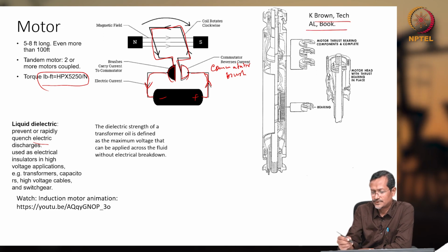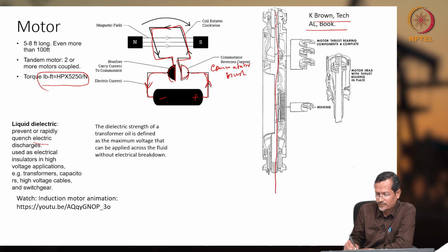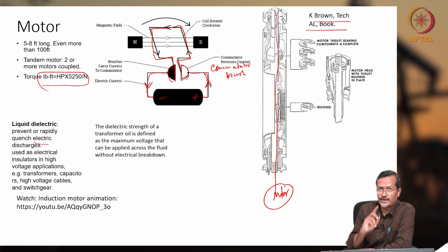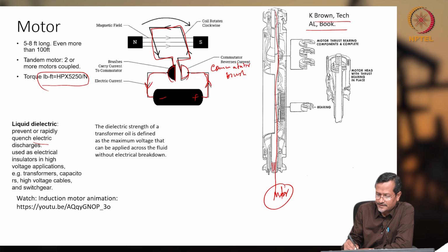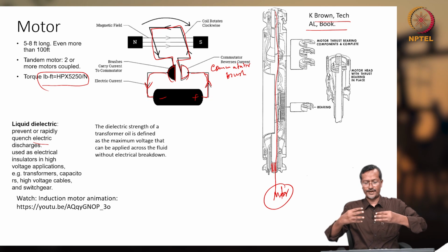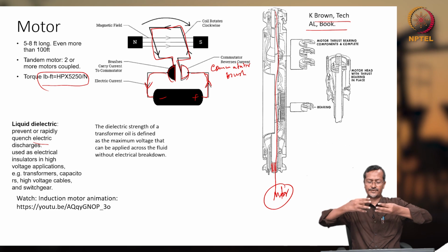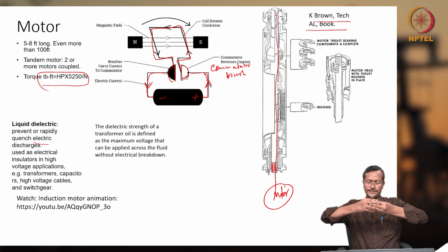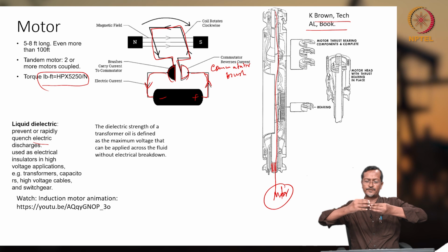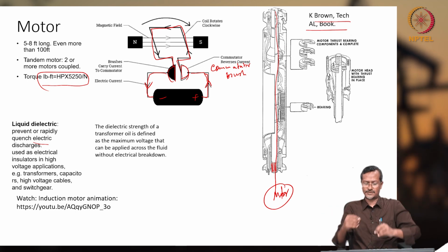This picture shows one big shaft going from the motor. The motor will be giving torque. And this will be the connection, the motor coupling. So how to connect: one motor shaft is there, one turbine shaft is there, your pump shaft is there. So the pump and motor shafts will be connected like this, and then you will be rotating. Maybe there will be a keyway and coupling sometimes. Sometimes there will be a spline connection like this, connect it and move continuously.